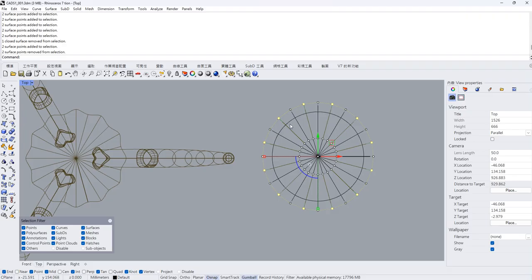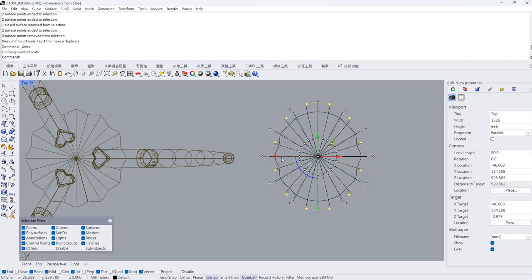So the next thing we are going to do is to scale down the distance between the border vertices and the center vertex. So let's just use the scale so that we can do that. Again, you can hold on your shift key to do the scaling so that you can get the shape like this. Or another way is that you can do it 2 times. So first one, choosing the X direction. So probably let's scale them to point 4.